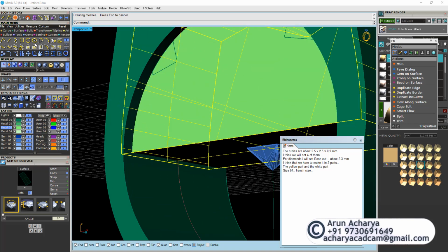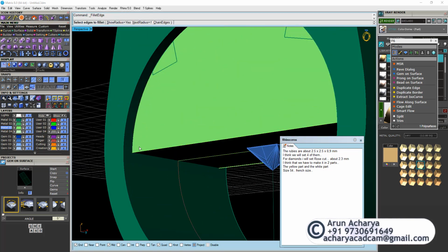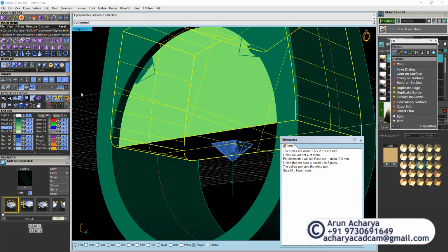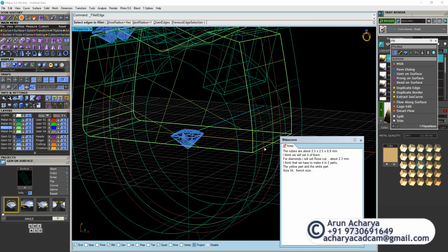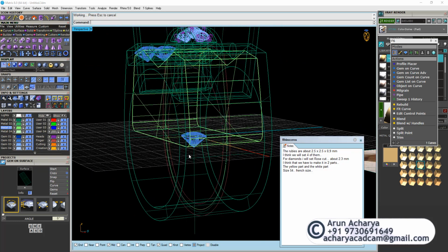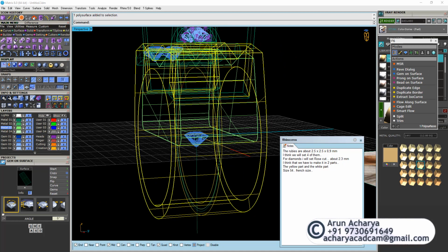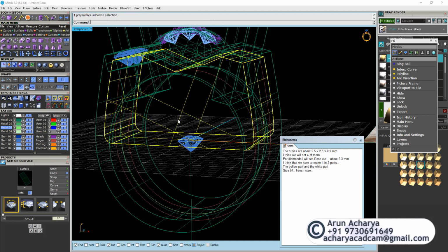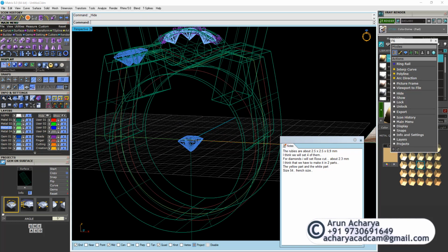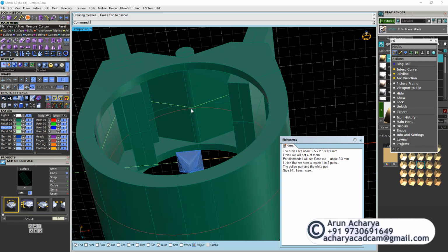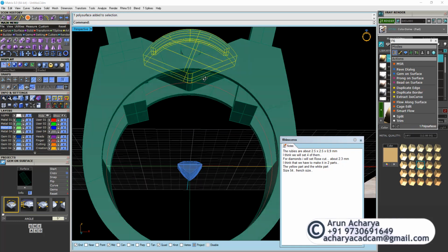And fillet this corner here, 1 millimeter is good, and this corner as well. Okay, and then you do a Boolean difference. Okay, that's it. Now if you see underneath, we got it nicely hollow, and this one we're gonna cut this out as well from this surface.